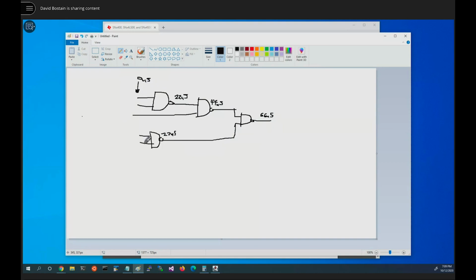So if we put this circuit in a box and it has a 66 nanosecond propagation delay time, we know that we better not expect answers any earlier than that, from the time we change the input signals till we look at it. So let's not bother looking any sooner because we may get a bogus answer. We said last time those are called glitches or hazards. They have subtly different meanings, but I'll let you explore that.